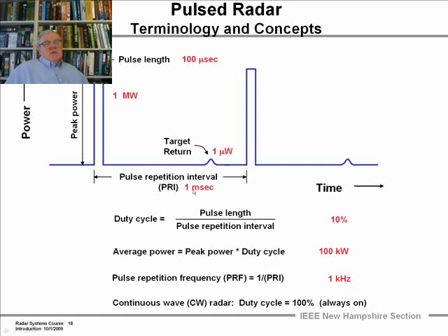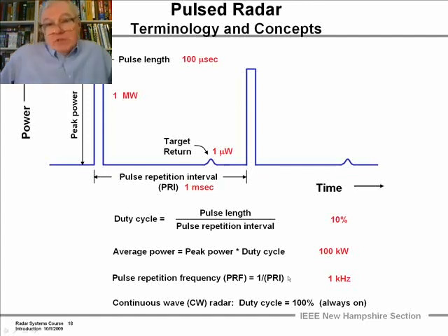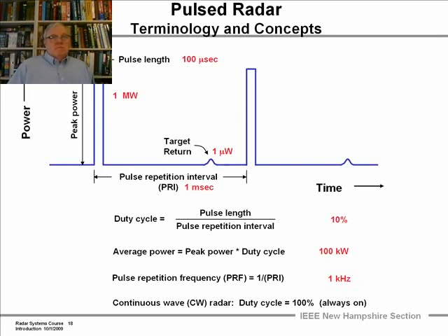You could get, say, 1/100th of a second up to microseconds, fractions of a microsecond, which would correspond to pulse repetition intervals of, as I go through my mind, easily I can think of radars that operate at 500 or 600 hertz. And also radars that operate, and we'll see later why, at 80 or 90,000 hertz.